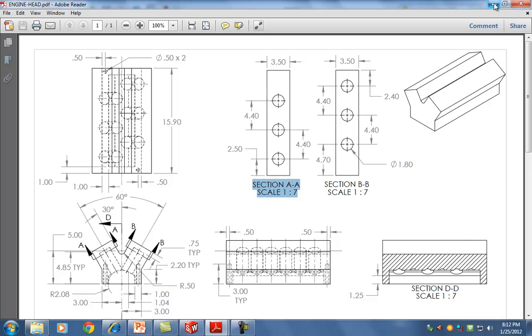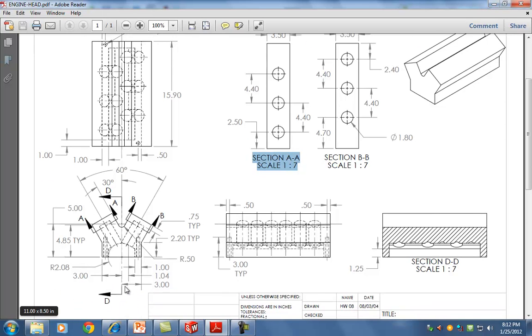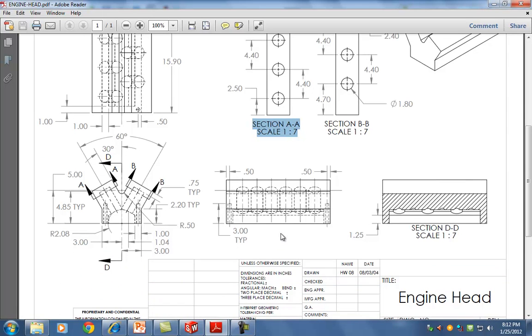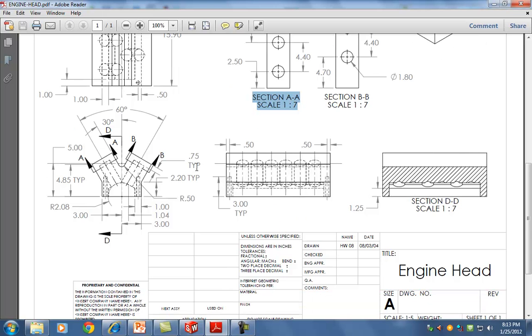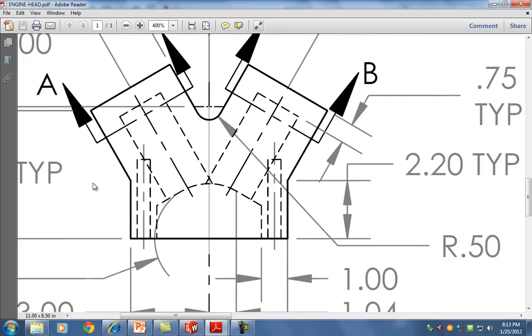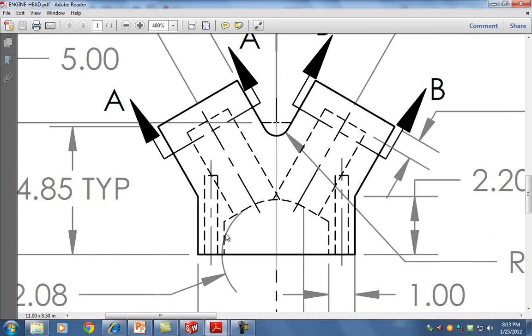All right, so from here, I also noticed that in addition to the cuts for the holes for the piston, there's also a cut here on the base. Do you see that? It's kind of like a rectangle, and then it kind of arcs up, and another rectangle. Okay, and by the way, how do you think this arc here is done? Fillet, right? I just showed you how to do fillet today, so we can do that.